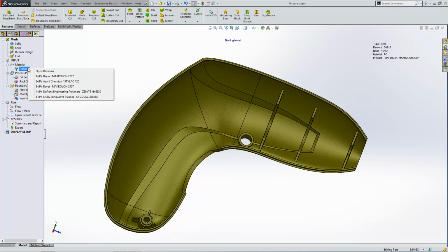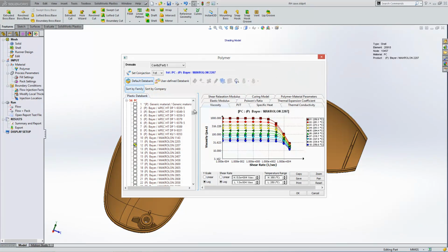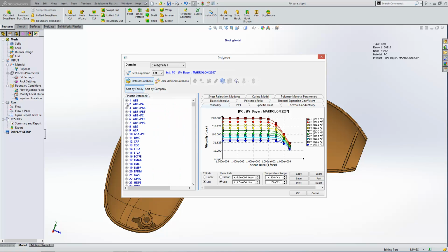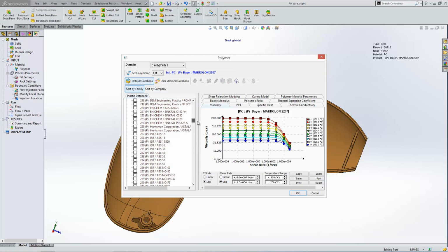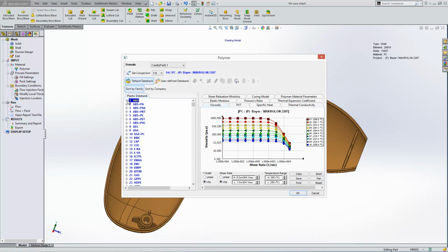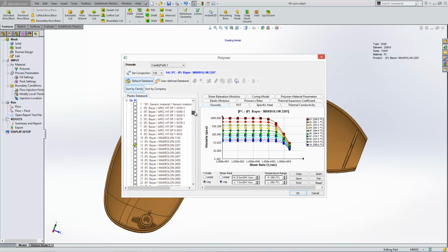At this point, I can then insert the polymer on my design. There's a huge database of polymers available within SolidWorks. You'll see that you've got them categorized under different plastic types with a number of plastics available in each one. You can use a search tool to find the specific plastic you're looking for. In this particular example, I'm going to use a polycarbonate in my model because I want it to be a fairly sturdy casing. So I'm going to use this one that's selected just here.